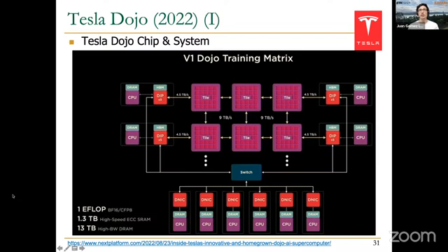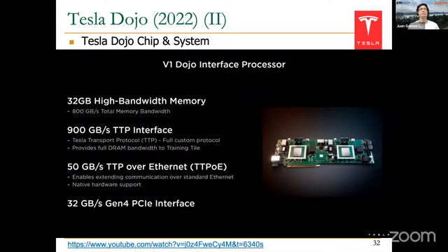Here you can see a CPU, a regular host CPU. They will also include this DIP, as we'll see, sort of an interface processor to communicate between the CPU and the tiles. These tiles are probably similar to a systolic array as well, to perform the matrix multiplications and matrix-vector multiplications that are necessary to do neural network training and inference. Observe also that the different devices have different sorts of memories, heterogeneous memories as well. The CPU may have conventional DDR-X DRAM, while this DIP, this interface processor, has HBM memory that provides significantly higher bandwidth.